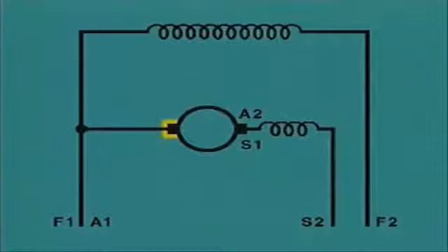In this case, we'll say that there is a reading, so this brush is all right. The same check is then repeated for the other brush. This time, we'll say that there is no reading, so this brush is faulty. A detailed check is then performed on the faulty brush and on the commutator. The brush is removed, and the brush's pigtail, the brush length, the brush's contact surface, the inside of the holder, and the bottom of the holder are all examined. In this example, the brush has worn down and it's too short.